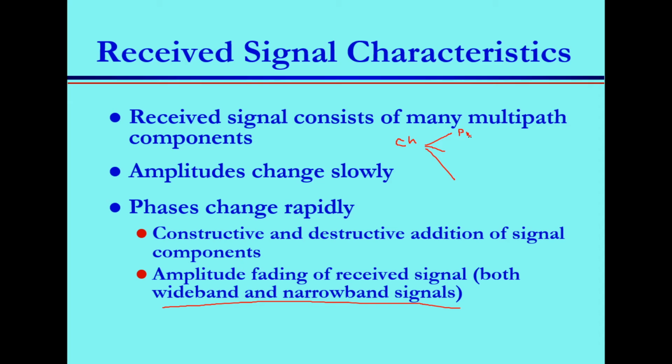The duration between the first and last, this corresponds to this, Tn of t, and this corresponds to this. And the duration between them is called the delay spread of the channel. If that duration is much shorter than the duration of your impulse, of your transmit signal, the symbol you transmit, the pulse, yes.